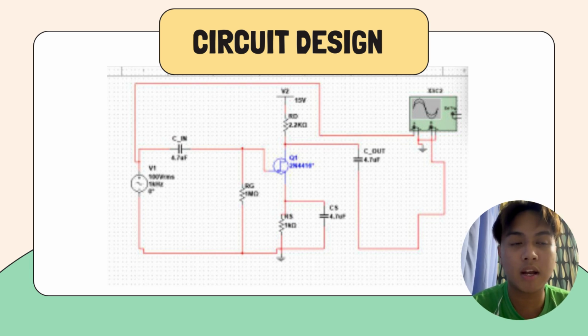We have used a 1 megaohm resistor connected to ground to keep the gate at 0 VDC, which provides the extremely high input impedance that JFETs are known for. This is the source resistor, which is set to 1 kilo ohm. As current flows through the JFET, it creates a voltage drop across RS, making the source positive relative to the gate. This successfully creates the negative VGS needed to bias the transistor.